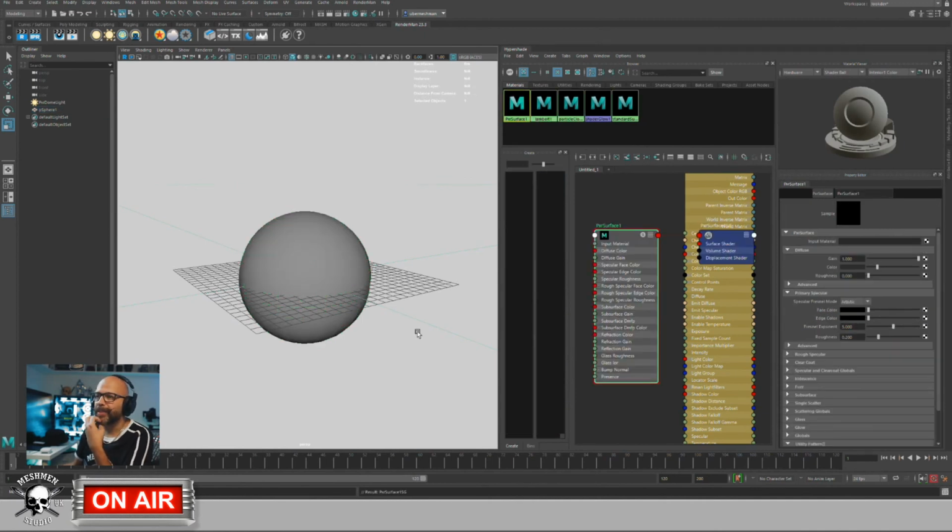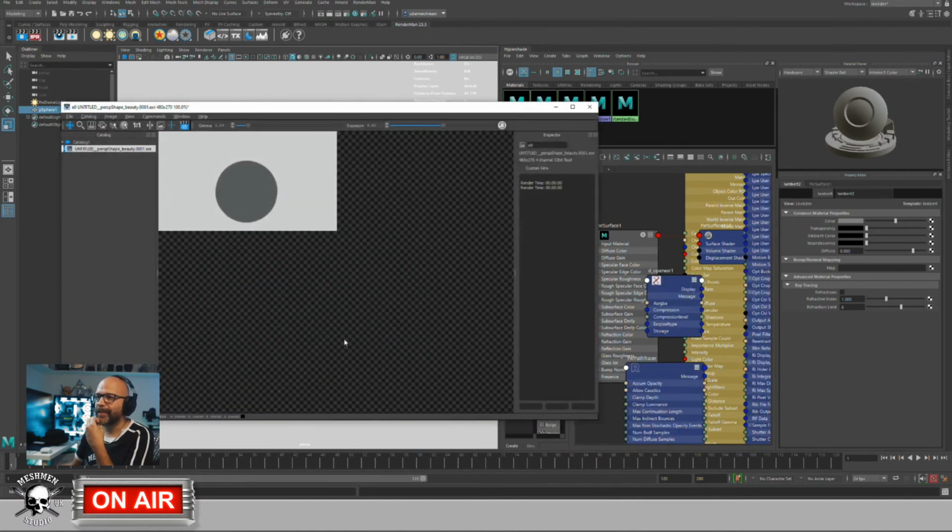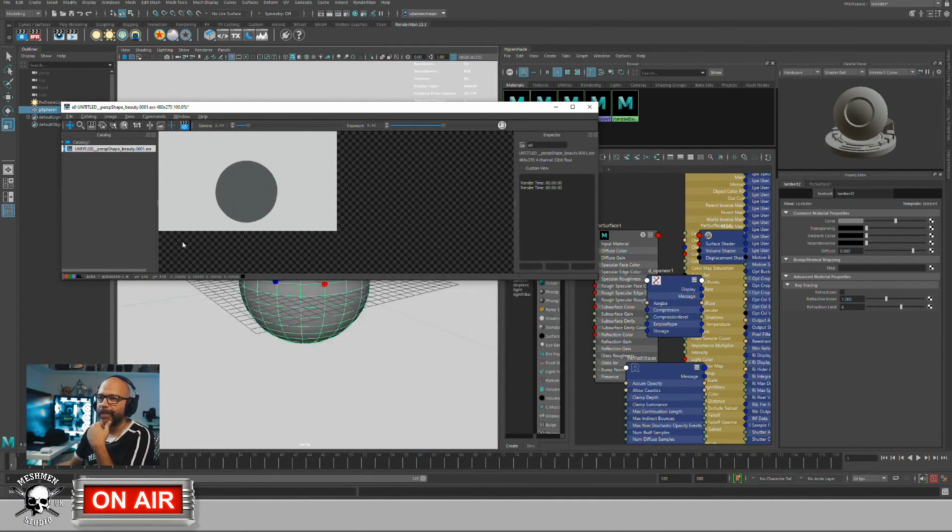First off, let's just apply a shader. I select the ball and hit this, the bath ball here. I like to call it the bath ball. And that essentially applies a shader. Now let's fire up IPR and get this rendering. Down here in this region you can see the pixel readout. It's gonna be hard to see from this live stream, I guess, but if I hover over the white background here, you can see it's 1, 1, 1. So I'm using essentially 1 in exposure onto the whole environment here.